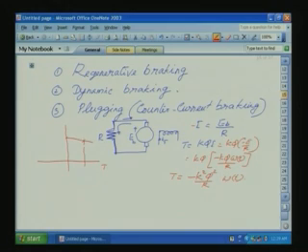Now, first you have to make the system come to this level. This level means torque is 0, so current will be 0. Then we have to apply the resistance such that a large reverse current, rated current, will go through this resistance. So the reverse torque will come here. From there, slowly, that means from this point it will come here.